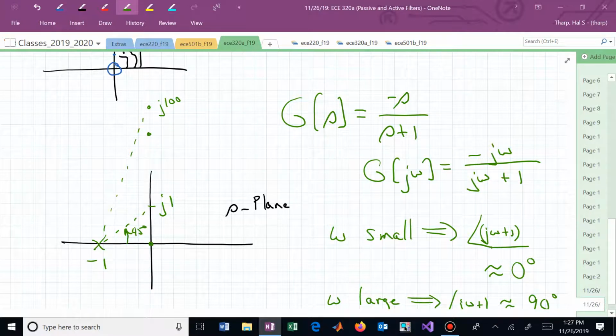So the fact that we have it is important that we keep track of, in the G of s expression in the transfer function, it is critical to keep track of what values of s either go to 0 for zeros, or blow up for poles, or when the denominator goes to 0. And those will be negative, and we want our poles and zeros for the Bode plots that we're plotting to be in the left half plane, which is the terminology for a minimum phase system. And the reason that is true